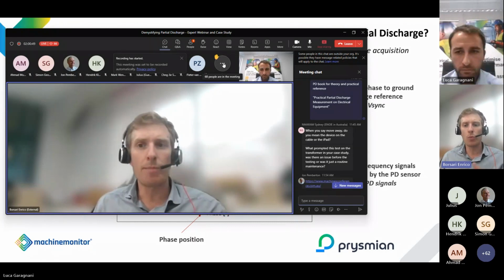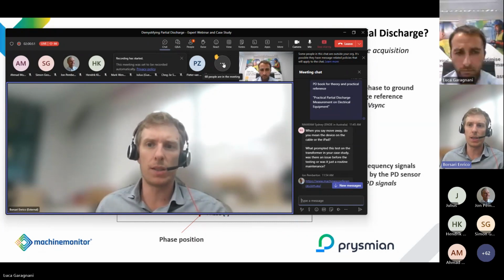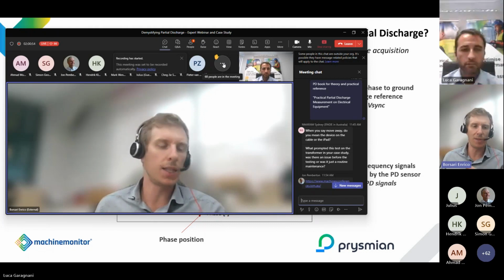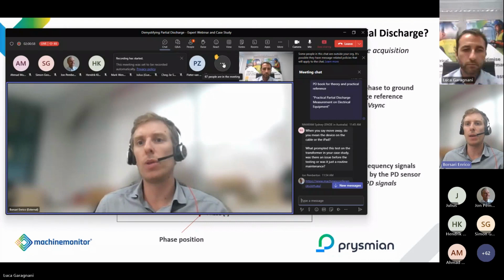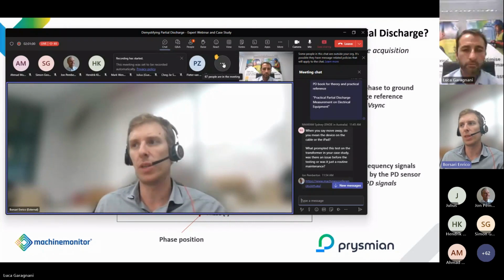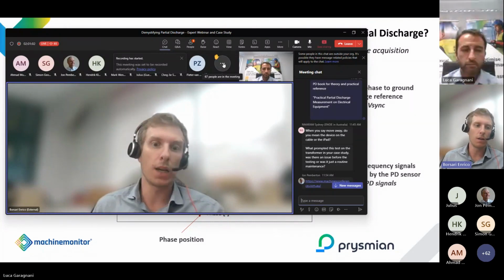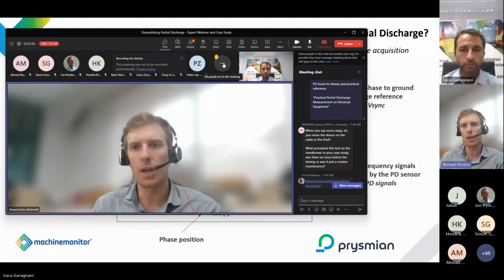At the end of your campaign, you will be able to compare, let's simplify, the amplitude that you retrieved from any accessory, and you will be able to pinpoint the source of the PD using this relative analysis.